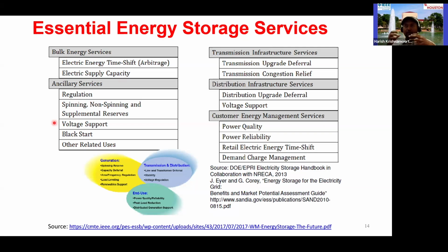So basically, when there is more energy, you can store that energy in the energy storage resources, and then during the evening time, when there is less energy available on the grid, we can actually send out the energy from the energy storage. So that energy storage is becoming very important. There are so many benefits. It also helps regulate the grid frequency, and it reduces the use of the spinning reserve, which are backup resources in case the supply and demand do not meet each other. So of course there are so many advantages that come with energy storage systems.